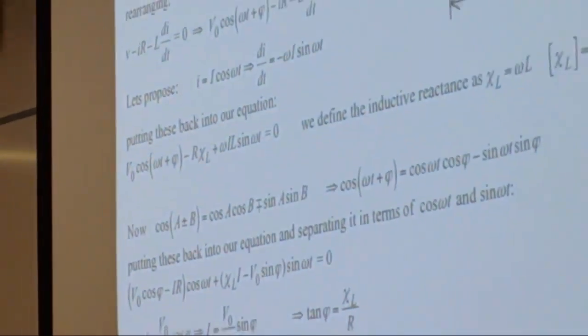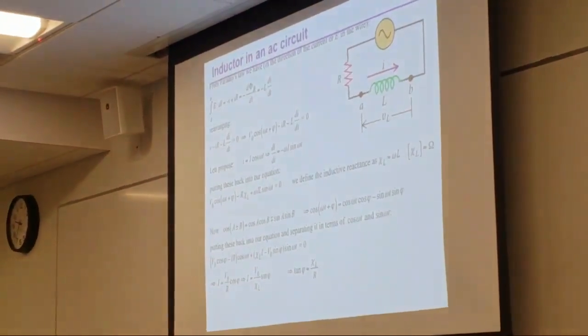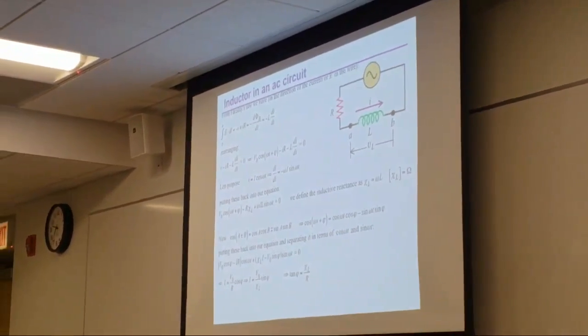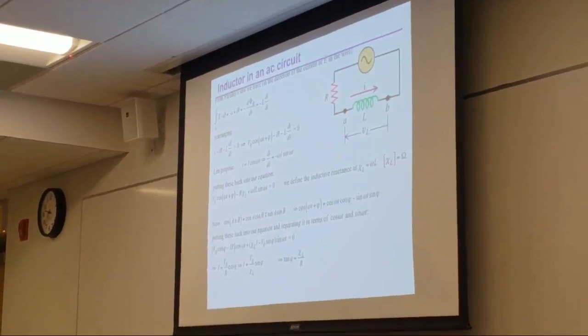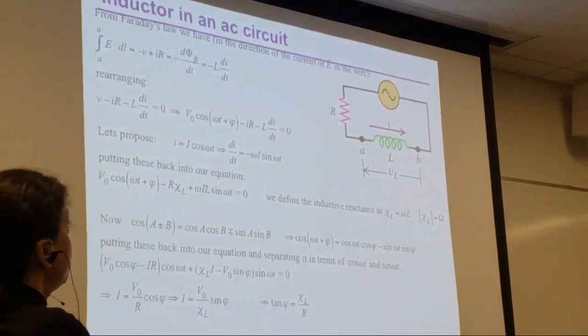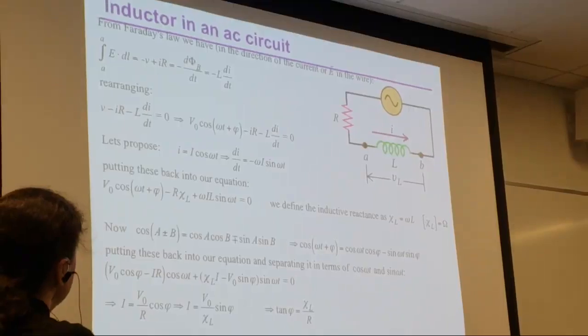All right. So now, because we have an inductor, we have to apply not Kirchhoff's laws. We're going to have Faraday's law. But you're very familiar with this because that's exactly what you're going to be answering about this evening. So the top corresponds to Faraday's law, and I go around the circuit from A to A, and I have the voltage across the source, plus the current times R, must be equal to the EMF produced, which is equal to minus the self-inductance L dI/dt.